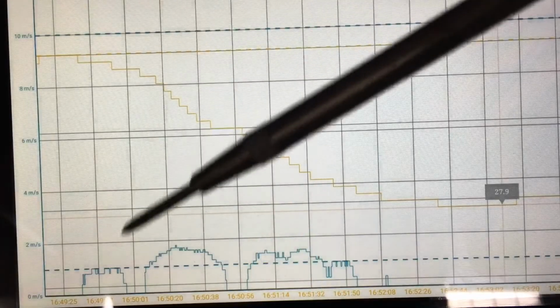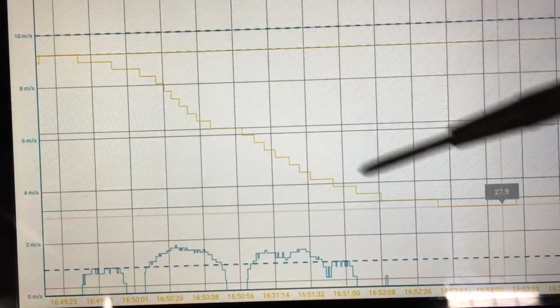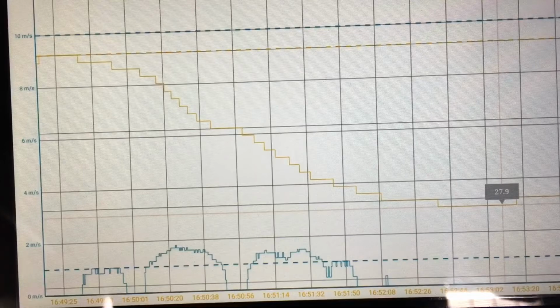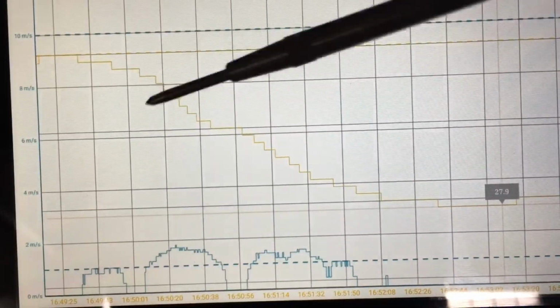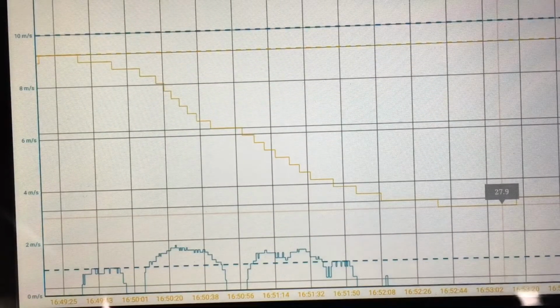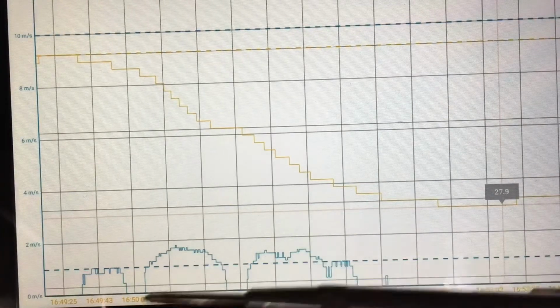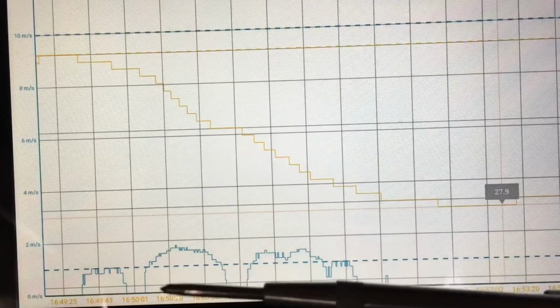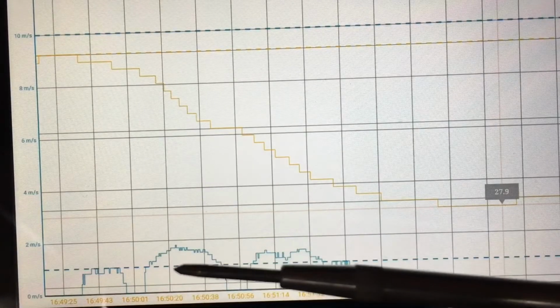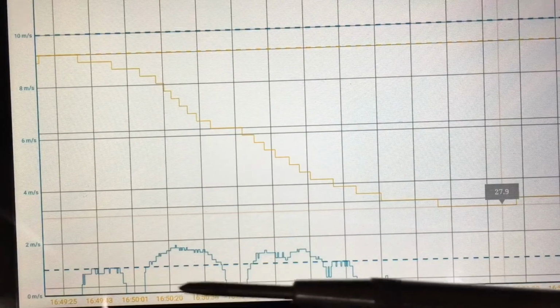So here we can see the blue line there. Disregard the yellow line, guys. That's the temperature from the ductwork. I think temperature came down a wee bit as we established some airflow through the ductwork. So again, with no fan operating and just a function of vehicle speed, the pressure that was building at the cowl area was forcing the air through the ductwork.